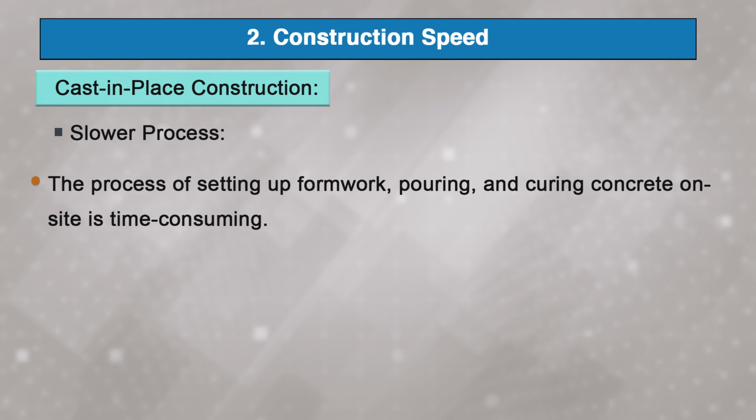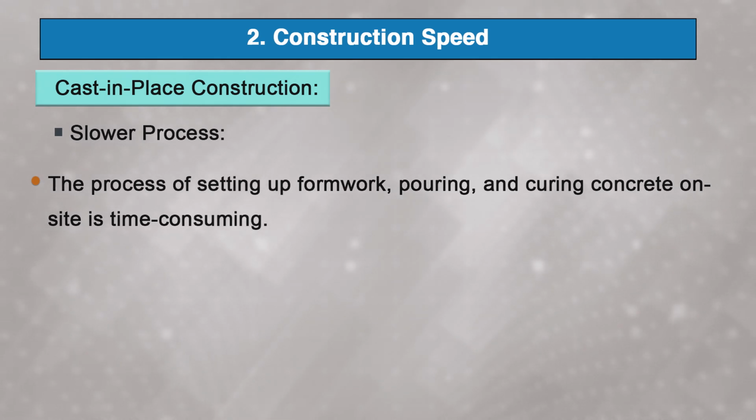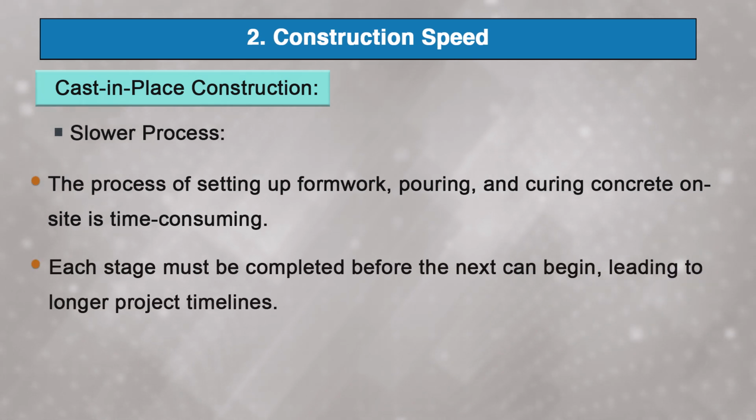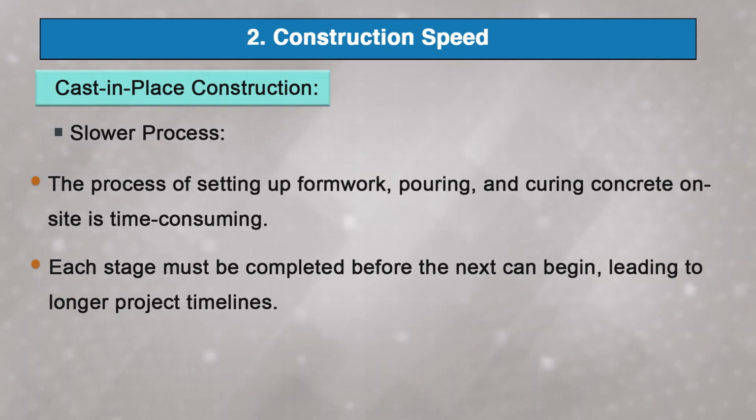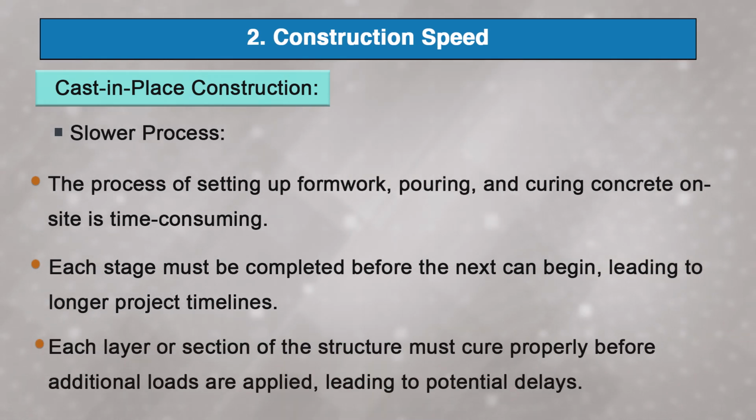As you know, this process of setting up formwork, pouring and curing concrete on site is time consuming. Each stage must be completed before the next can begin, leading to longer project timelines. Each layer or section of the structure must cure properly before additional loads are applied, leading to potential delays. For example, for a multi-story building, each floor must be poured, cured and formwork dismantled before the next floor can begin,